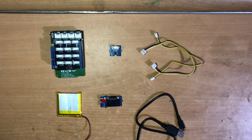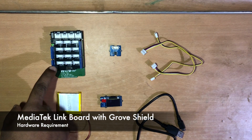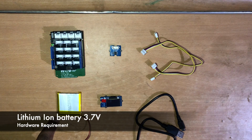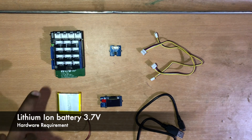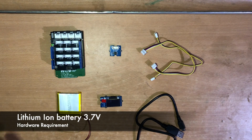So friends, let's get started with the hardware connection. What you require for this exercise are these components. The MediaTek LinkIt board along with the Grove shield that we also used in the previous tutorial. We will also require a lithium ion battery. This is required because whenever we are trying to upload the Arduino code to the MediaTek LinkIt board, we need additional power. So for that the battery would be necessary.